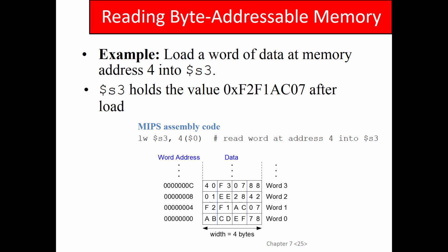So how do you deal with that? The byte address is usually the lowest order 2 bits, so it's 0 to 3 of the address. So if my word address is 3 and my byte address is 2, which byte am I getting? Well, obviously I'm in this word, word 3, but which byte? If my byte address is 2, which byte? F3? That's right, if it's Little Endian addressing.